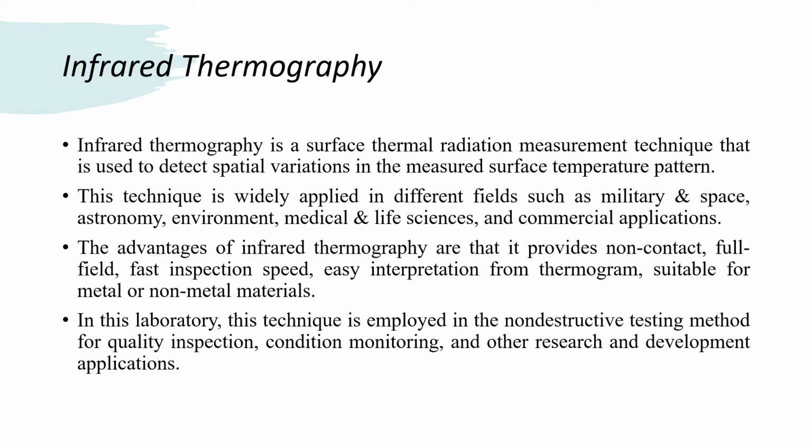The advantages of infrared thermography are that it provides non-contact, full-field, fast inspection speed, and easy interpretation from the thermogram, and it is suitable for metal or non-metal materials too.